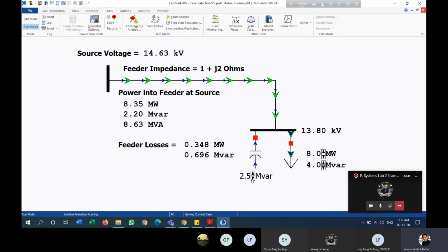So you need to write down that for controlling the sending end voltage to receiving end voltage, you can control it by the shunt capacitor. And also you can write that for improving the power factor, you can use the shunt capacitor. This will be another good reason.